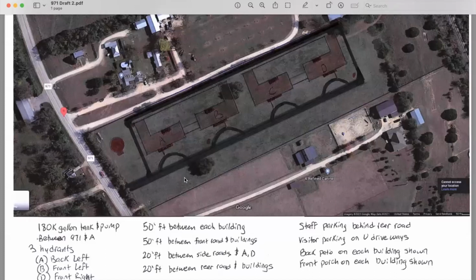So straight across. Here's the property line here, and then here. This is 300 feet across. So I'm working backwards then, right? Here's what I know. My building is 110 this way, I think from memory. Then I know I had 20 feet there, so that's 130. Then I have my road at 26 feet, 156. It goes right up against the property line. Maybe there's like a foot. We'll call it 160 to round off. This road here is another 26 feet, so it's 185-ish. And that left me with 125 feet roughly from here and here.